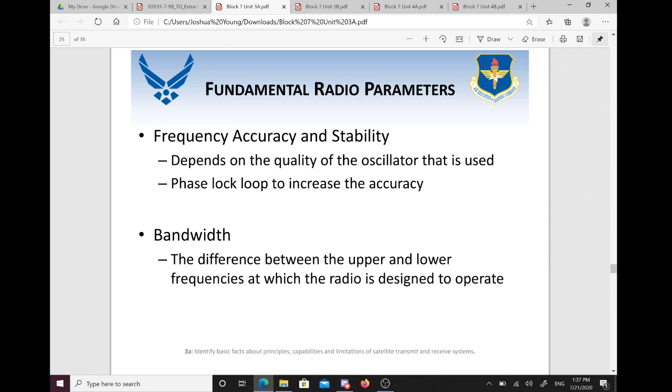And then you should have talked about how quartz oscillators are less efficient than atomic oscillators because they're affected by the piezoelectric effect, which we can control the temperature of, but not the aging, because that is inherent to the piezoelectric effect, and over time your quartz oscillators will degrade. But your atomic oscillators just count the oscillations of highly stable atoms within the oscillators being used, and that's what creates your time. But your frequency accuracy, how accurate of a clock your radio is providing, and the stability of your transmission is determined by and dependent on the quality of your oscillator.